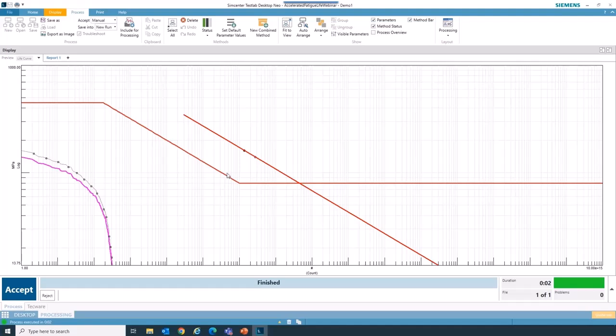So the life curve will be something which is parallel to this, and it will show points and the relationship between the stress level and the cycles for failure. So for this particular load history that we have provided, this is showing the stress. And so when we increased from this stress, we increased by a factor of 1.15. So that is what it is saying. That is the point at which it will present the corresponding number of cycles for failure.